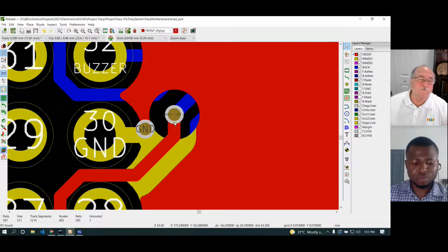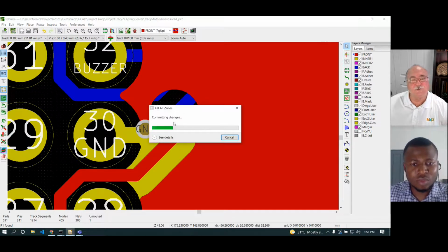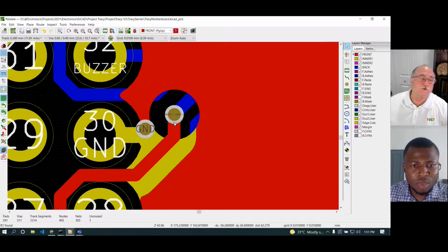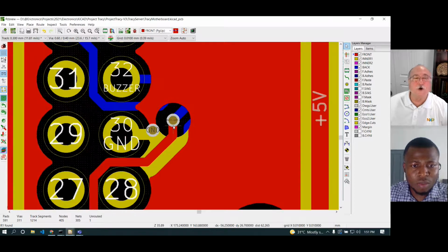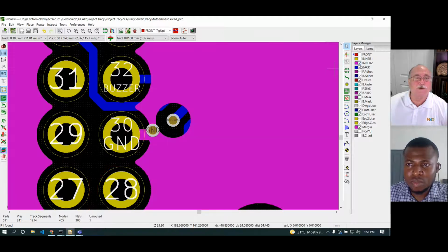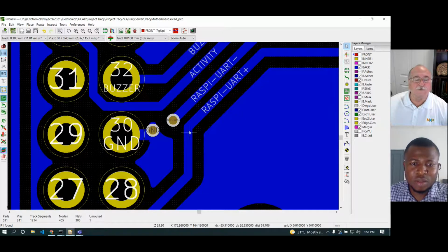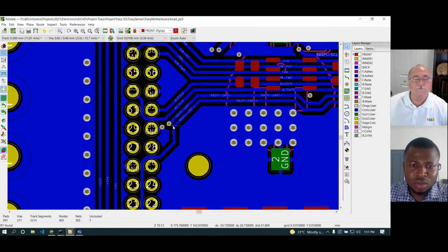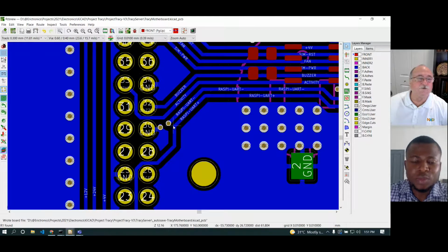And then my rule is, either move things so that you can get a second via in there, or you delete that piece of copper. You don't want to have a ground on one side and then a length of copper, because that does present a potential space for field to be collected.